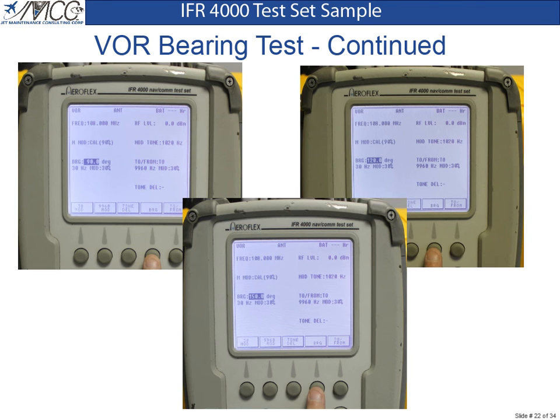Continue to press the bearing soft key and check that the indications on the HSI and RMI match for all of the remaining 30-degree increments of the compass card. This means check at 90, 120, 150, 180, 210, 240, 270, 300, and 330 degrees. If all of the indications match the bearing displayed on the test set, the VOR bearing check is good.